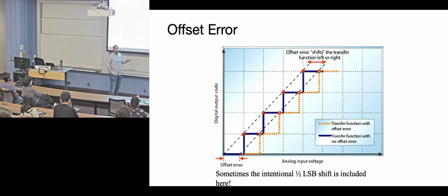That's easy to correct if you have a calibration step. You can go through and measure a few DAC values, or put a known analog voltage in, and then say, oh, I'm consistently off by this error, and now this is just a software update to account for a static DC offset. That's an easy error to fix. In the production world, you have to have some way to detect that without putting it on a test bench and measuring it for every device.